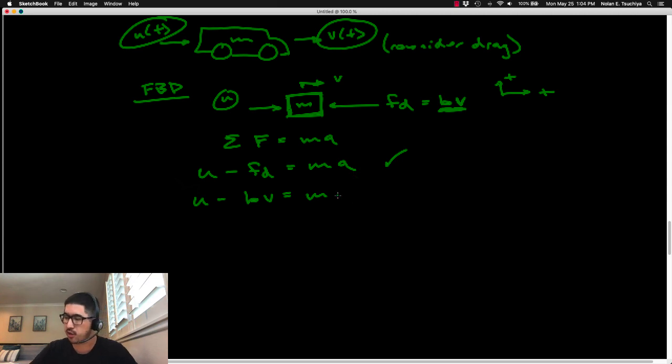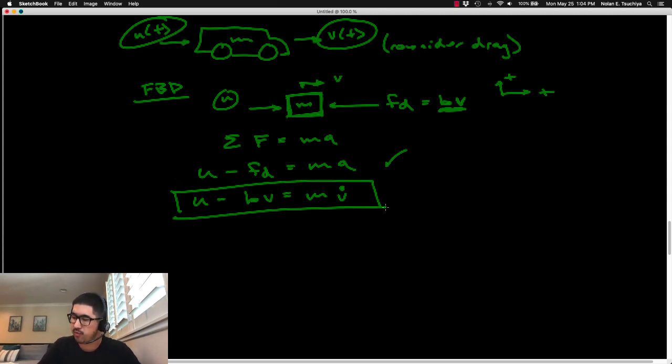So the acceleration can also be expressed as the time derivative of the output velocity. Now if we do it this way, what we've basically produced is an ordinary differential equation that only contains the input-output variables and maybe their derivatives, along with some scalar constants. This differential equation is what we want.